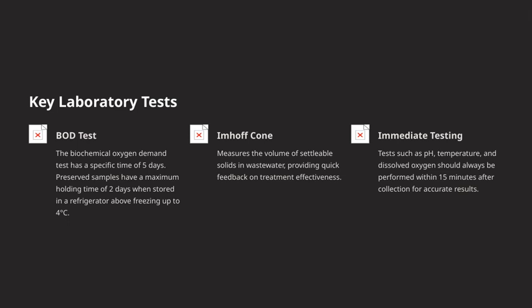Next, we have the Imhoff cone, which is a simple yet effective tool for measuring the volume of settleable solids in wastewater. These solids can tell us a lot about the treatment process's efficiency. When solids settle out quickly, it indicates that the treatment system is working well, providing us with quick feedback. Finally, immediate testing is crucial for certain parameters like pH, temperature, and dissolved oxygen. These tests need to be performed within about 15 minutes of sample collection.